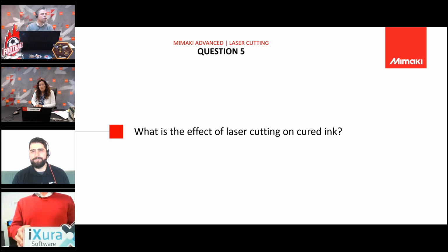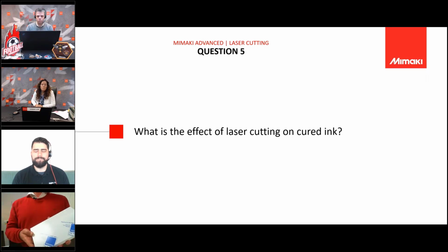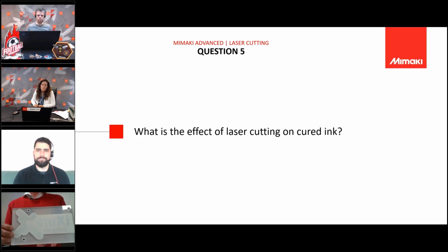But for acrylic, you get really nice results if you print on the backside. So in this case, we printed from the backside. It makes a very nice look because it's shiny. Also, the print comes out very nice on the backside in a reverse way. And for production, I have the raw material here. You can leave your protective cover on the front side even until you hand it over to your customer. So it's protected for shipping and installation, and you get a very nice surface until the end. For production, you add your artwork and your edge marks on the back side of your substrate. And what is also a good point is to have this white background. It makes the colors come out much better.